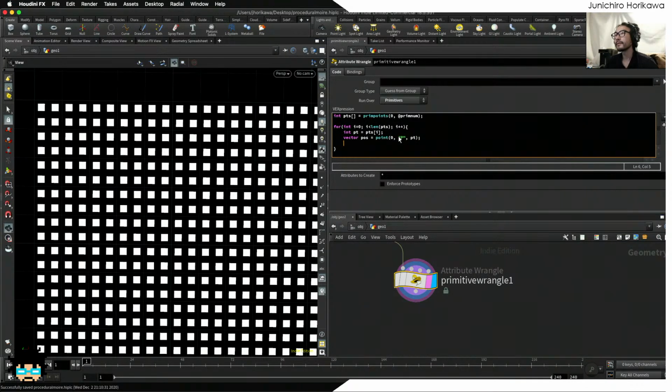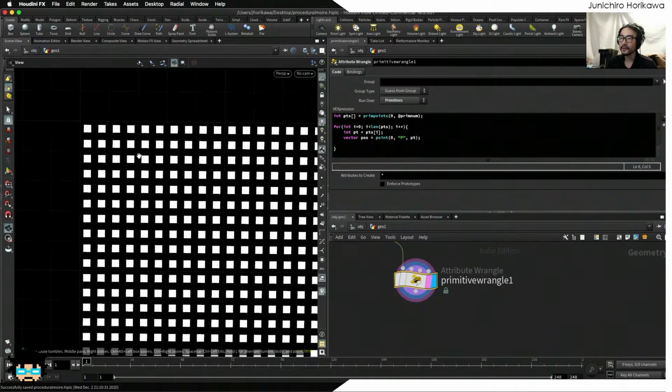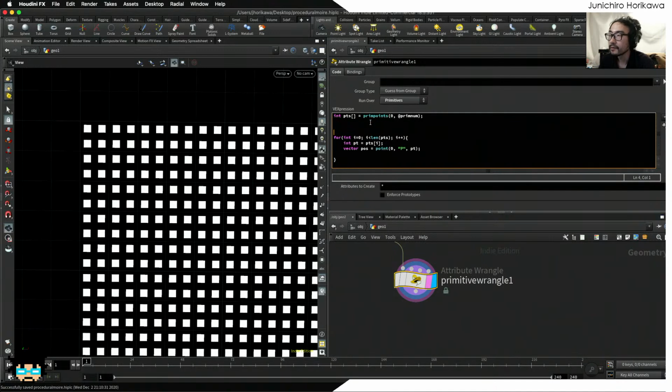at this point. Now let's try to use some noise function in order to move these points per primitive, and since it's per primitive, I want to keep the size of the box the same for each primitive, so I shouldn't create any noise value inside the for loop, but should do it outside, using the center point position of the primitive as a seed.